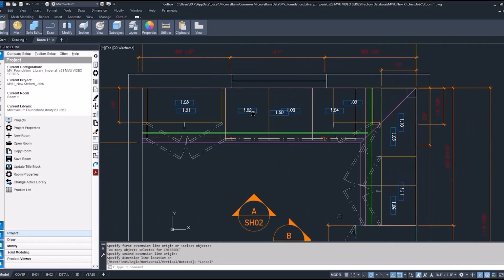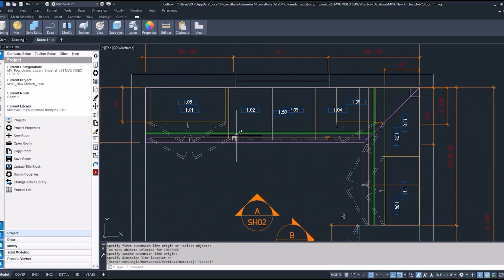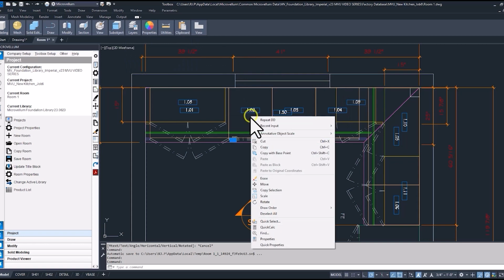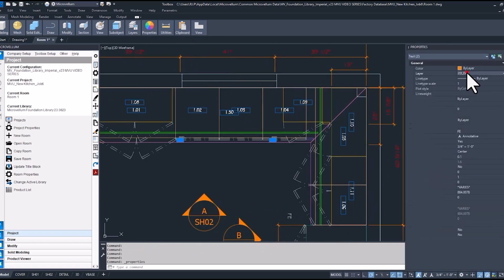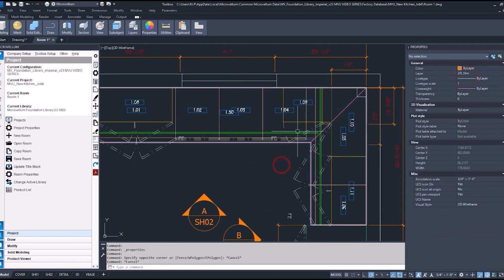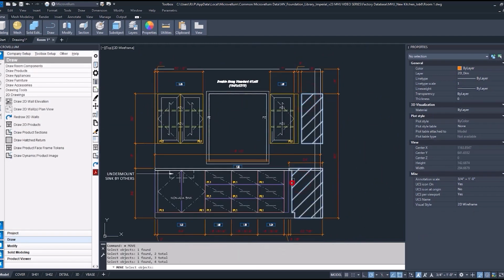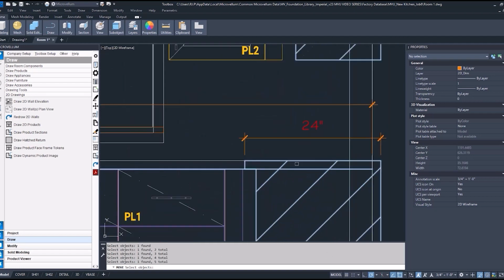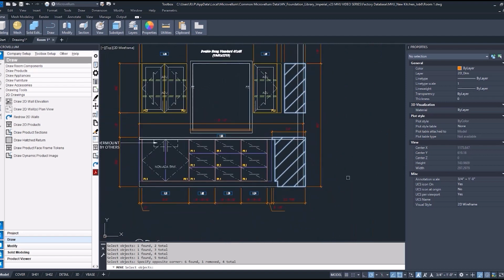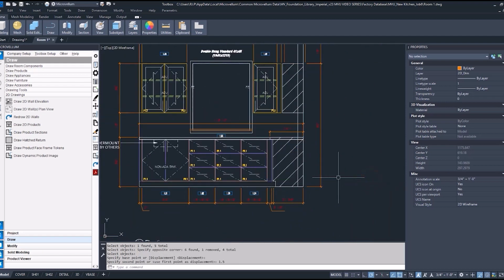Now over to our plan view, we can double check to make sure everything's updated the right way there. Because my layer was on 2D dim again, let's change that. Okay, that looks good. Elevation drawing. Okay, so it looks like all we have to do here is move our hatch return over that 1.5 inches using an AutoCAD move command. I accidentally grabbed that countertop, so I just unselected that, holding down my shift key, and move that over 1.5 inches.